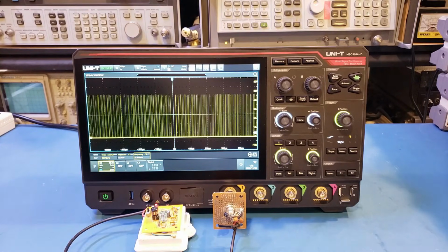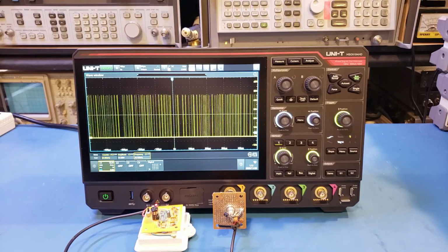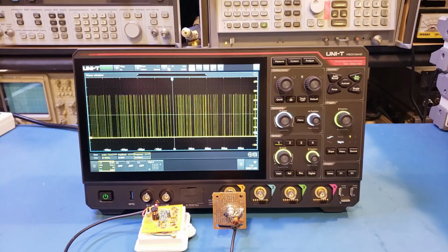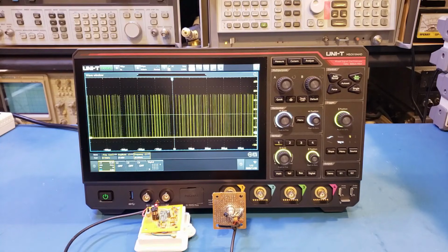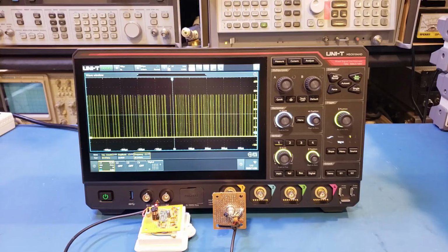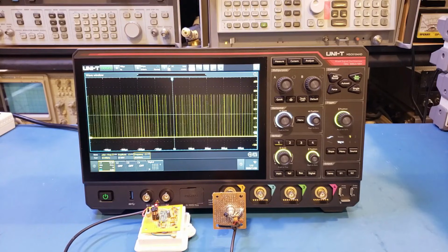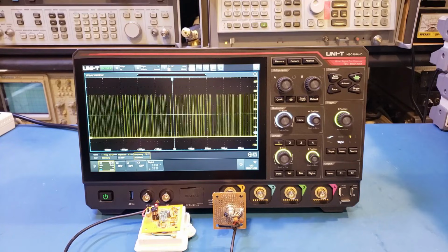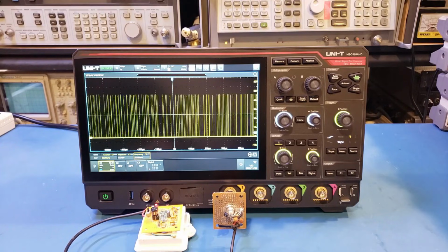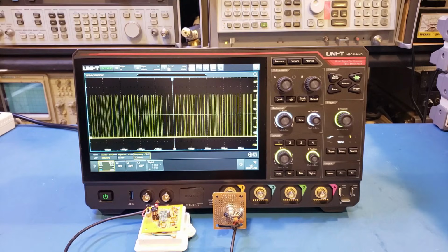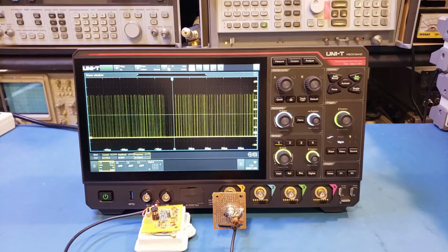the actual pulse. And in my review, if you recall, in the 300 MHz bandwidth MSO5304X review, I knew I was pretty close to the limit of the avalanche pulse generator because the rise time is just right around the limit of the bandwidth. And on the 500 MHz scope I tested, the obtained bandwidth is actually lower than 500 MHz, so I know the rise time is probably not that much faster than 1 nanosecond. But this time we actually have a much higher bandwidth scope, so we can validate that.